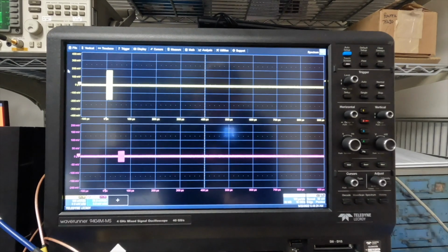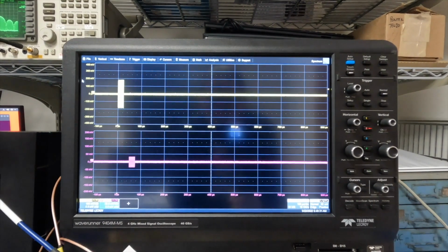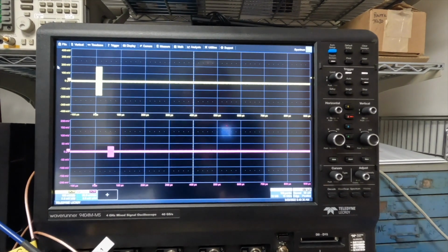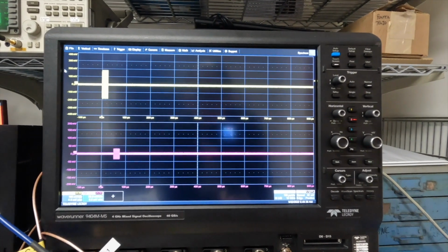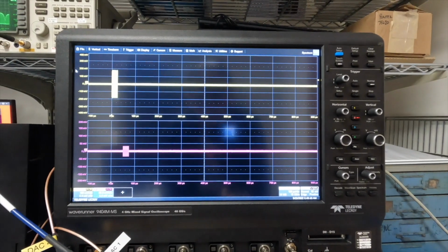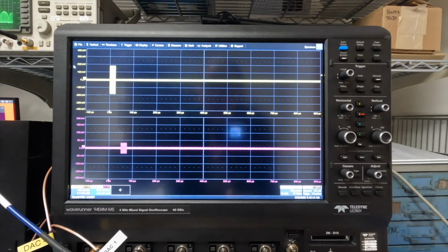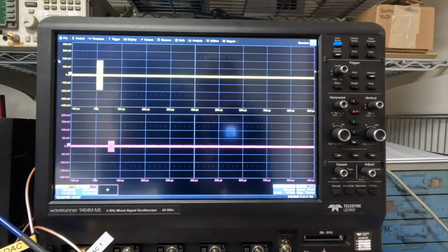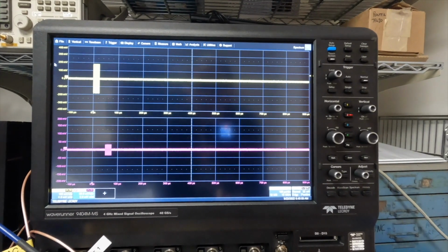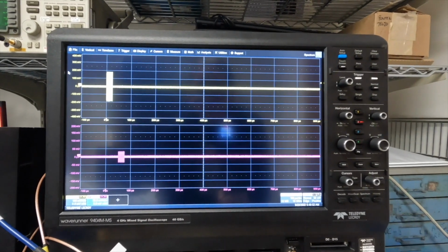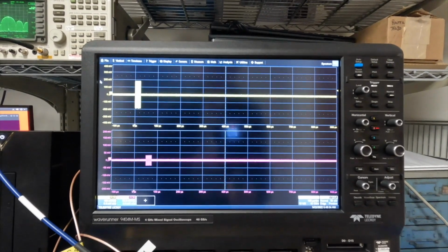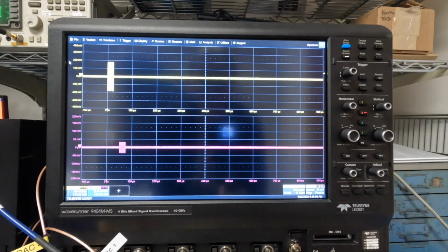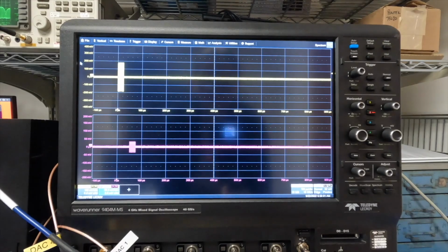Okay, so the next and last feature we're going to show in this short series of the DRFM Jammer today is the ability to not only place the multiple false range targets where we want them in both time and Doppler, but also the ability to change the amplitude of the relative returns as seen by the victim radar. So for right now, we have a transfer function between the input to the A to D and the output to the D to A. And what we're calling 0 right now is we can go up higher in amplitude and also lower in amplitude.